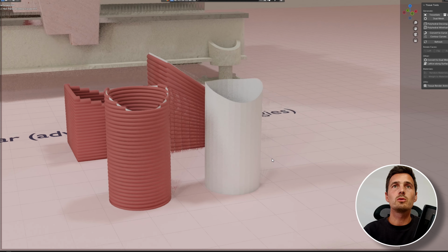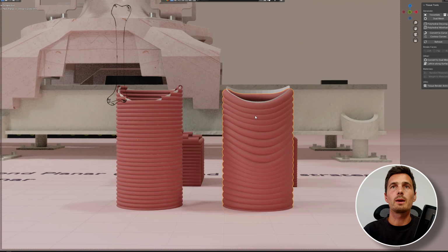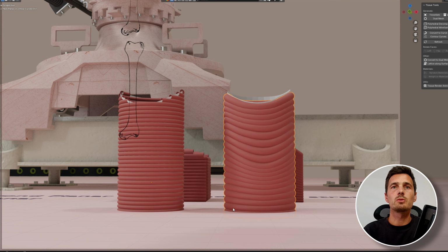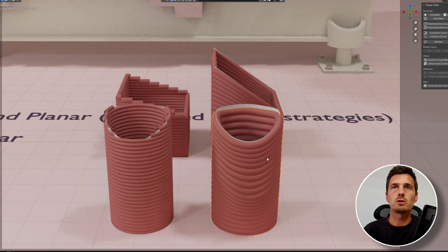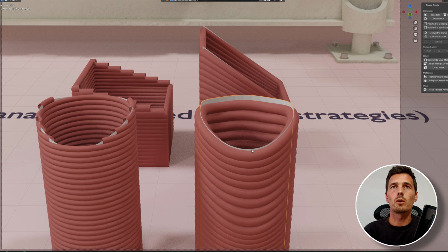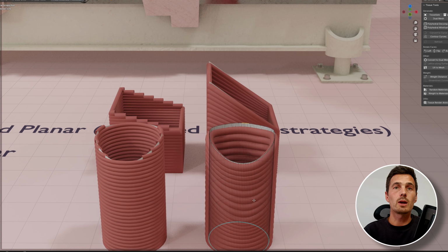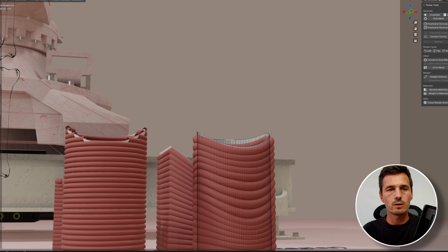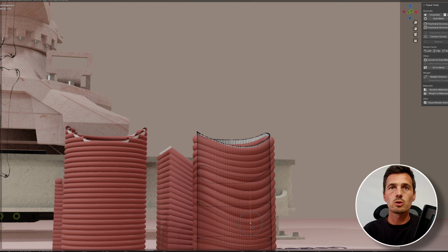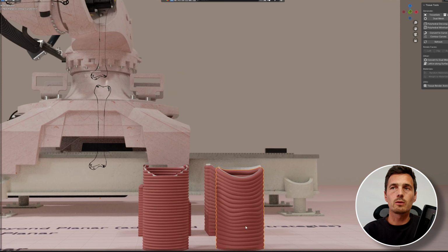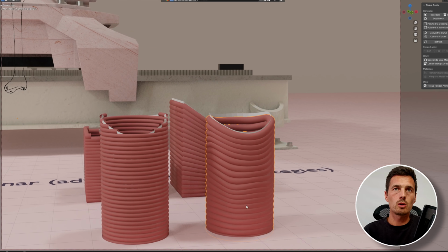So the way to do that is to apply non-planar printing layers. So that's what you see here. In the beginning, the layers are straight, and slowly you see that they transition towards the form on the top. You can do that gradually, or you can tweak it. So now it will have a little bit of a different form. Also with that one, you can play around how you want your layers to look like.